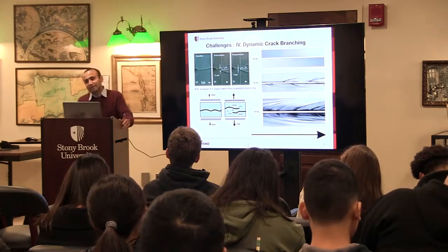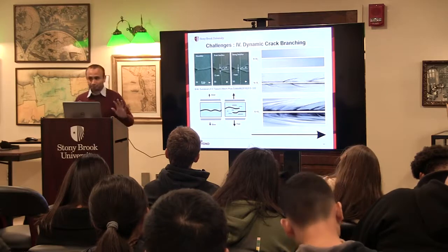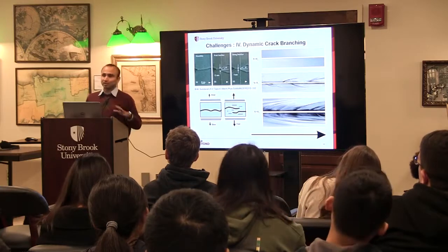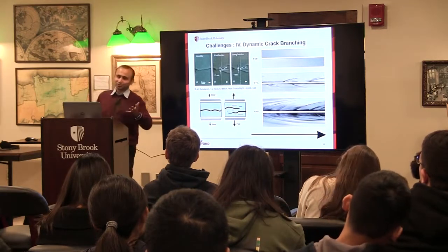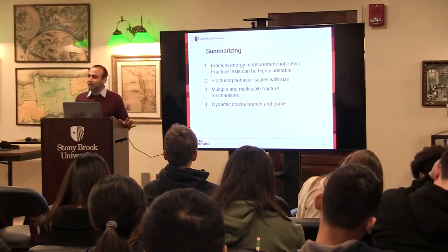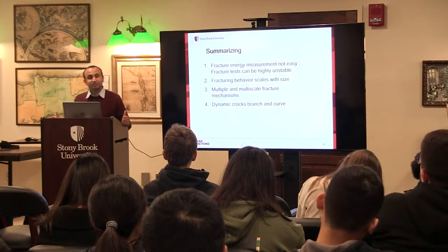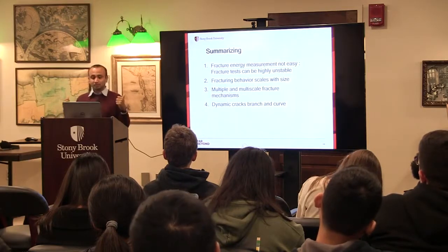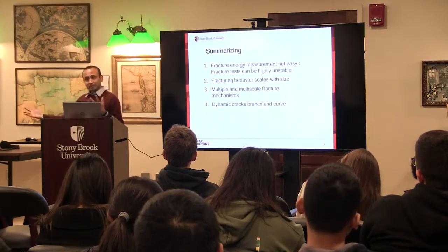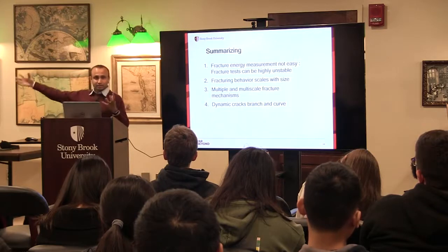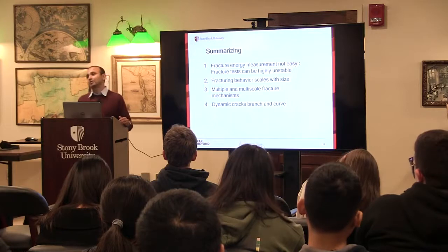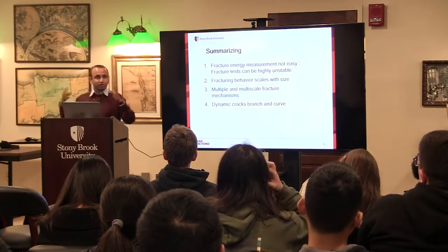So primarily we will tackle these 4 challenges, which I will show. I will not show too many technical details, of course. I will just show you the challenges directly over time and some of our ongoing work. So to summarize, we have these 4 challenges. 1, that fracture energy measurement is not easy for composites. The tests are highly unstable. 2, the fracturing behavior depends on the size. It becomes more brittle as you increase the size of the structure. 3rd is that fracturing itself is very complex and it consists of multiple mechanisms depending on the direction of the loading.